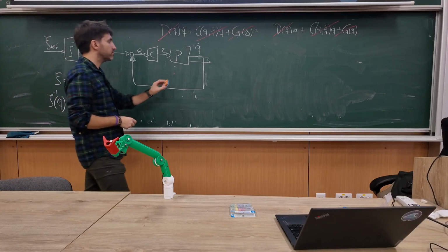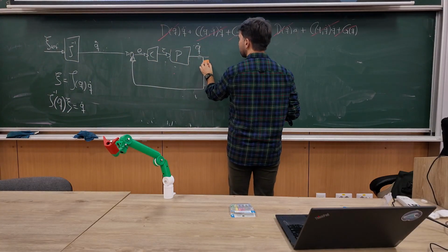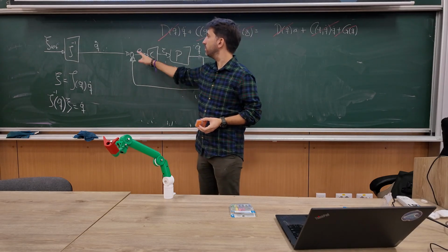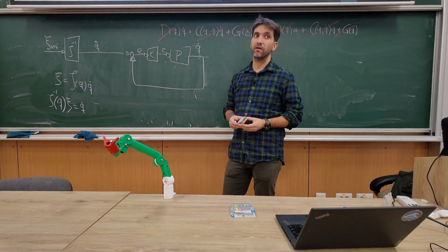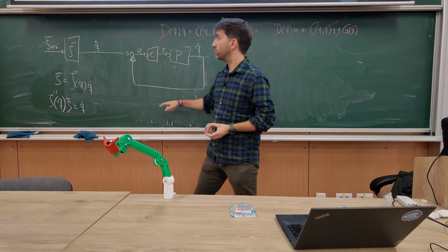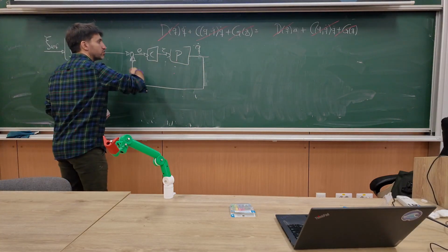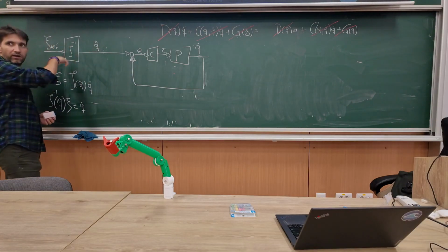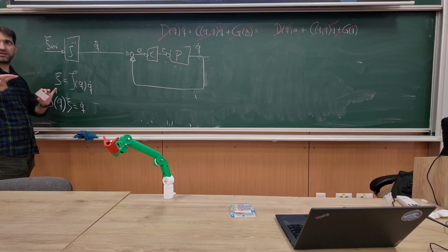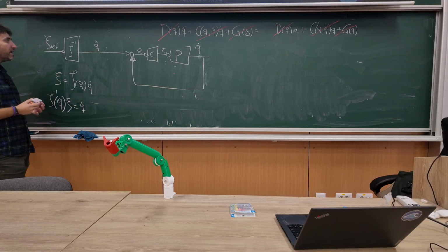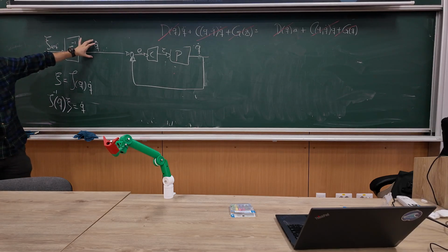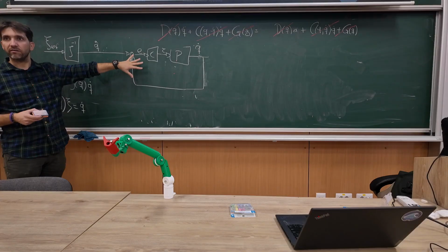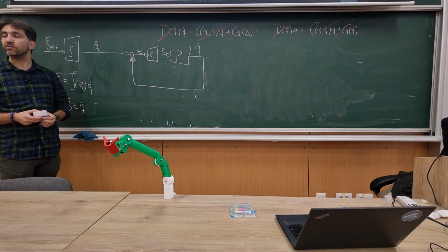There is one thing missing though. What feedback? Now I have to take joint velocity and transform it with the Jacobian into end effector feedback, end effector velocity. All right, so I close the feedback here. My feedback is here because here is the controller. If I put another feedback, I need another controller, right? And I don't want to control at the end effector level, as we said. But again, I assume I know the Jacobian well enough, and that's a good assumption, right? So I decompose the end effector velocity to joint velocities, and then I control just here. And that's all.